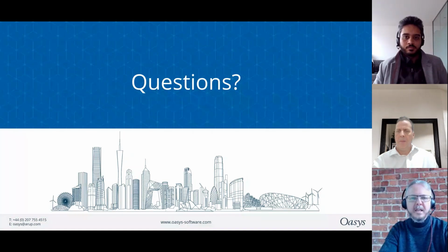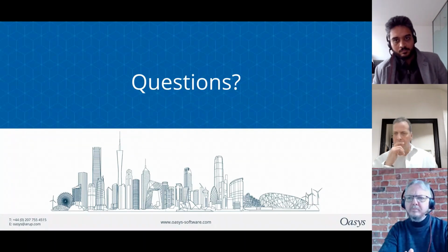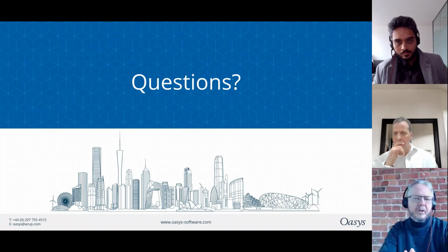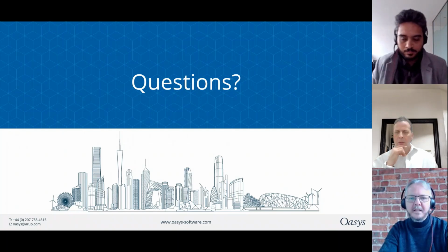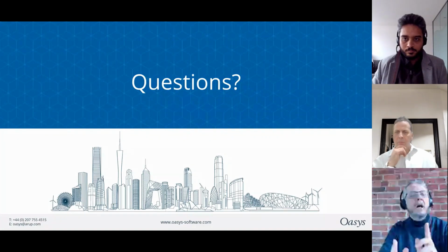But yes, you can then set up all the pile soil interaction coefficients as appropriate with the granular and cohesive soils, and then run it with the piles as well. I mean, Crossrail example is quite a good example of a piled raft analysis. There were some major station boxes designed using GSA on that project. Also, not Crossrail, the Elizabeth line, as we should call it now.